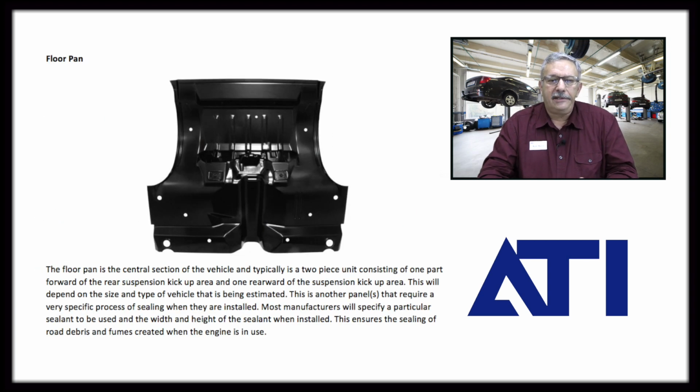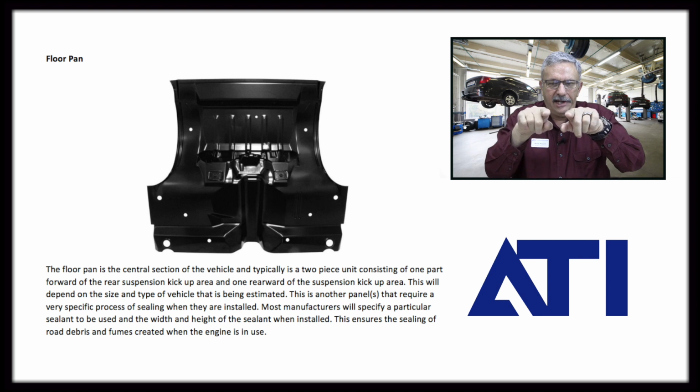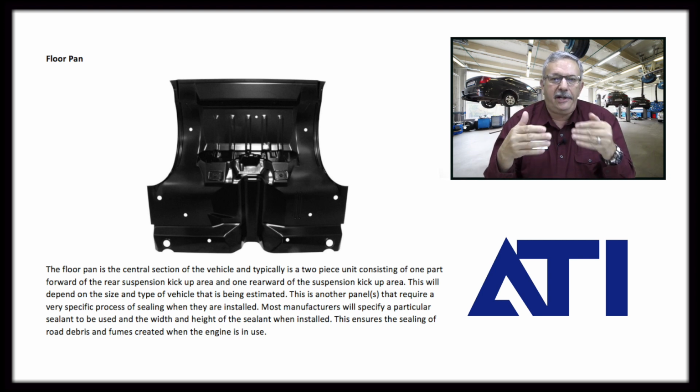Speaking of floor pans, this will be the next item we're going to talk about. This is a major structural component in the vehicle. Now, some folks will say, well, it's just stamped steel, etc. Well, each of those stampings is there for a reason. Any convolution, so I'm looking at a part, any convolution that I see, that is there to add rigidity to the part or strength to the part.